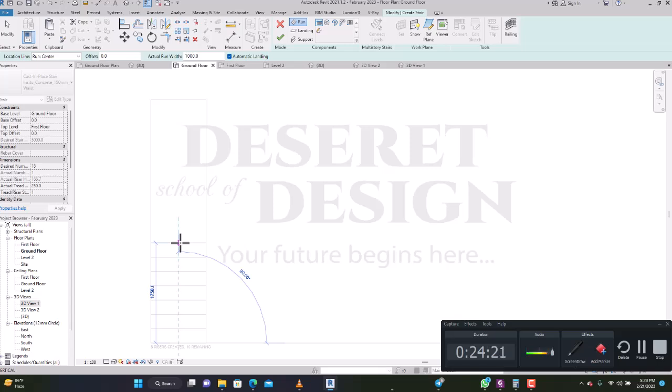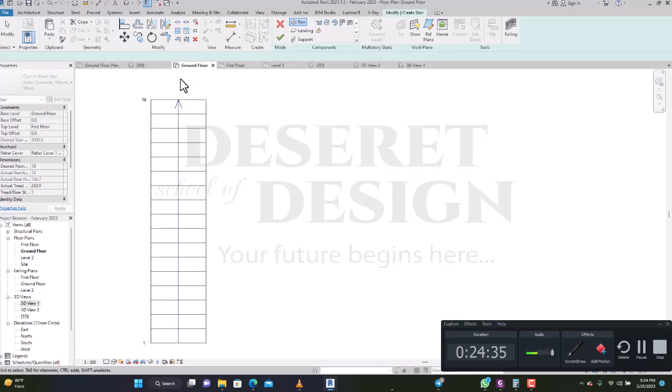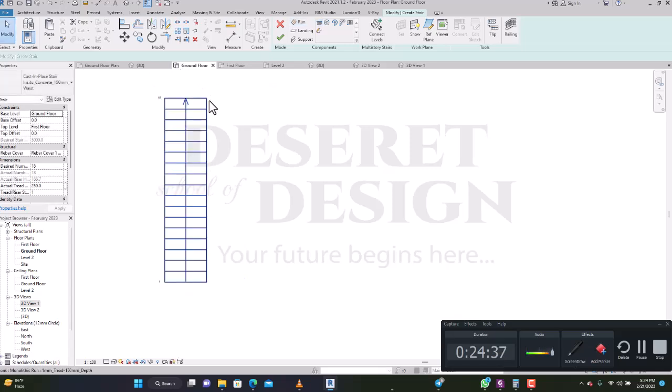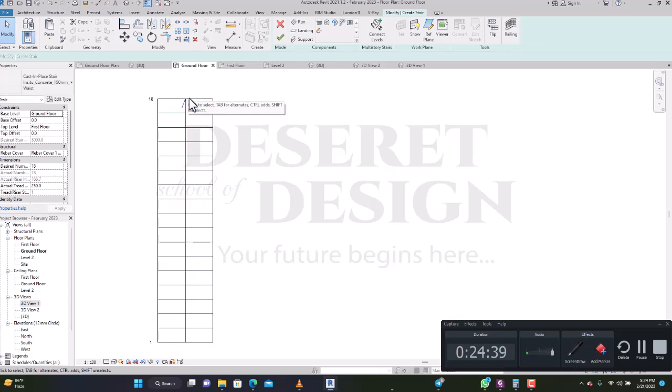Okay, now you can also look at where all your stair will end up. So when you are drawing your stair, you should go beyond where the distance is. So I just continue moving and go beyond, then I will click. The moment you click, your stair has been created. Now you have not accepted it yet. Maybe you might want to do some changes. Now you will see that you have 18 out of 18. It means that out of the 18 stairs I need, I have drawn them. Do you get it?